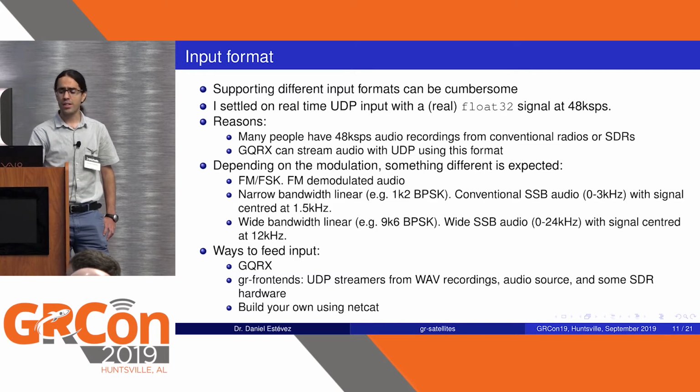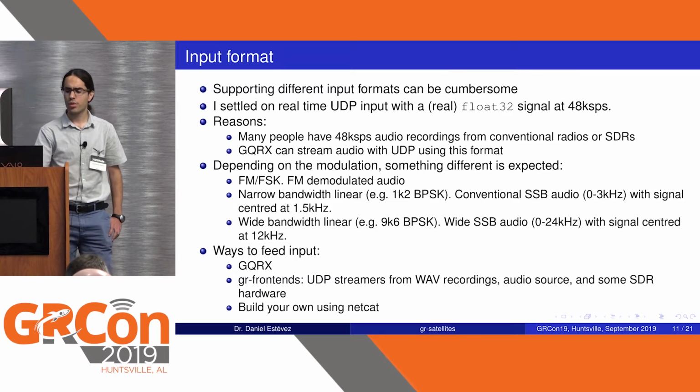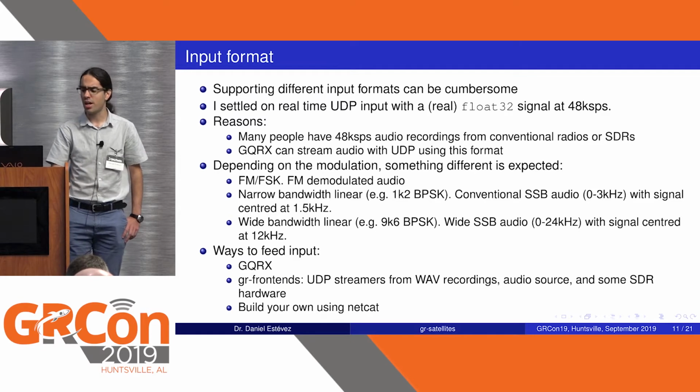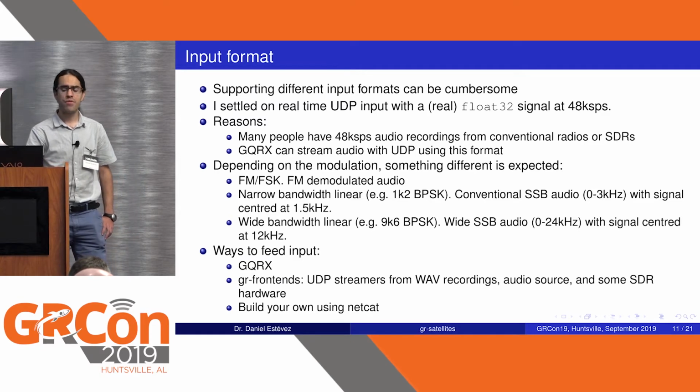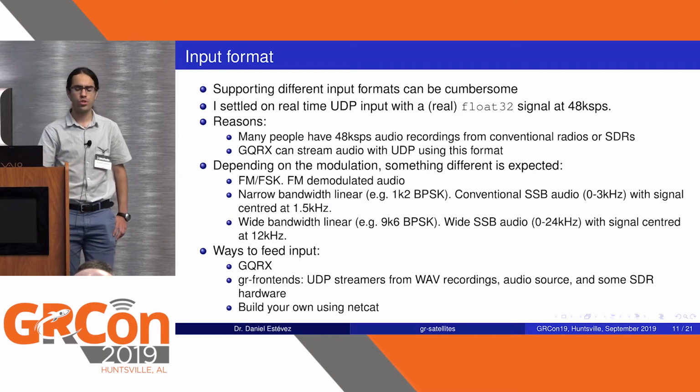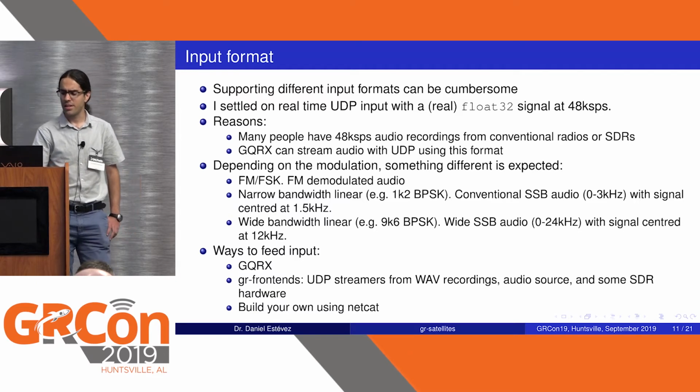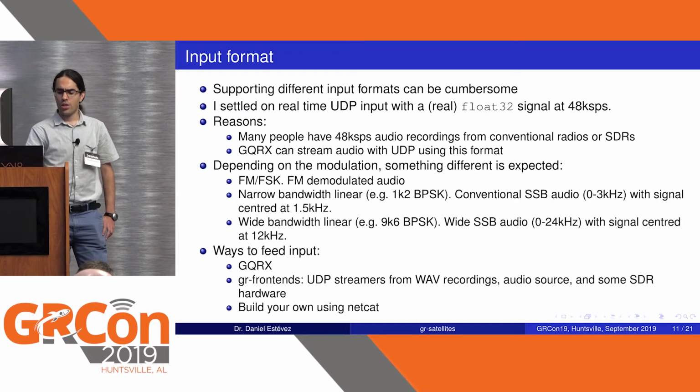The main reason for that was that GQRX, which is this popular SDR application, already has a feature to stream the audio using this very same format. And also many people have recordings taken from conventional radios using the audio sound card on the computer in this format. So depending on the modulation of the satellite, something different is expected as this kind of audio signal that you input into the decoder.